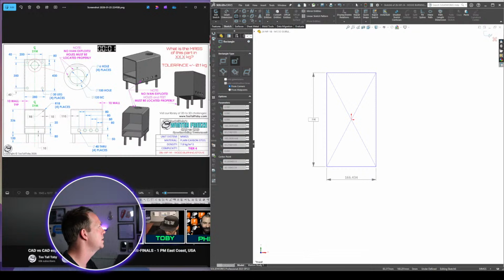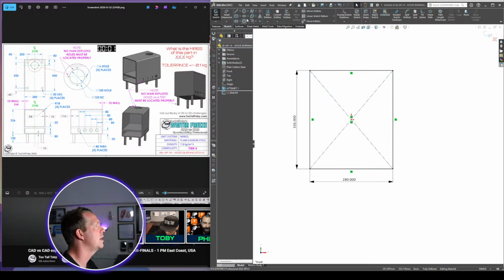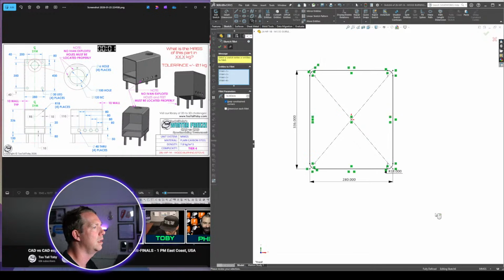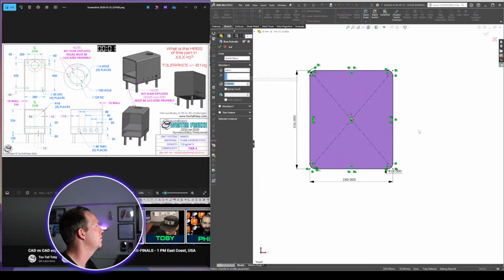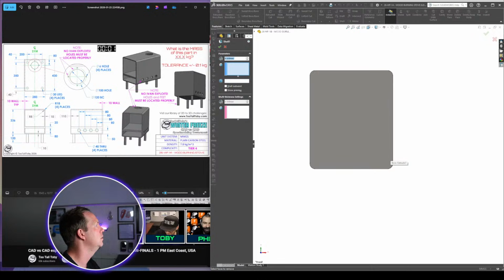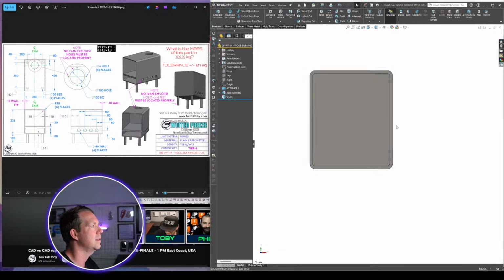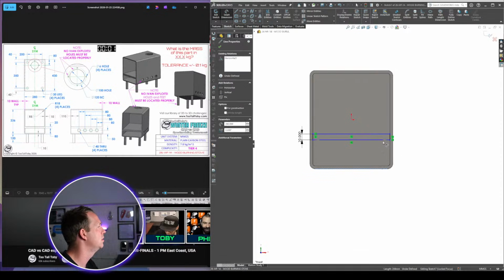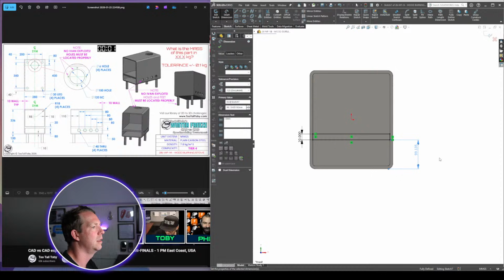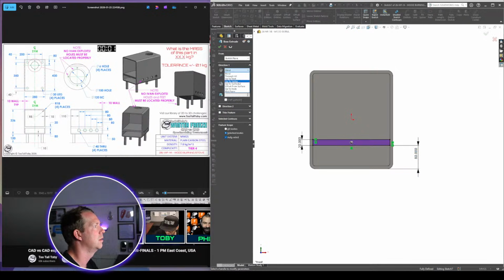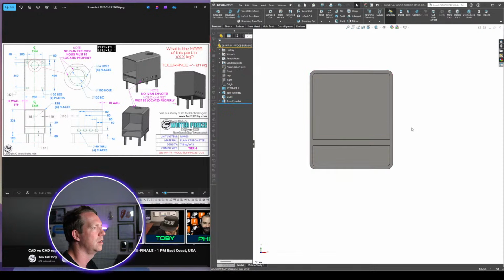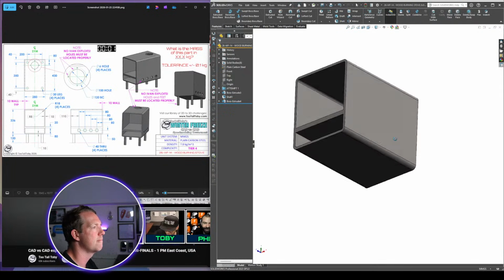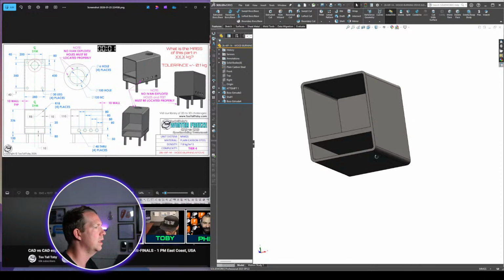336 by 280. Get those radiuses in and then extrude the whole depth, which was 430. And shell was 10. You don't even need to change your views to get to this point. Sketch on that back wall, rectangle, 20, drop it, dimension, 80, extrude, up to surface, edge. So I did all that without even changing my view. That's definitely an efficient way of doing it.